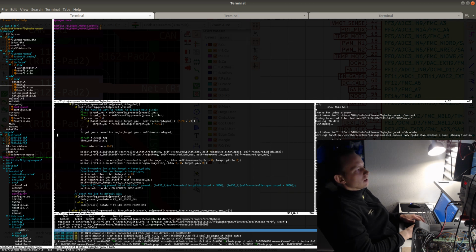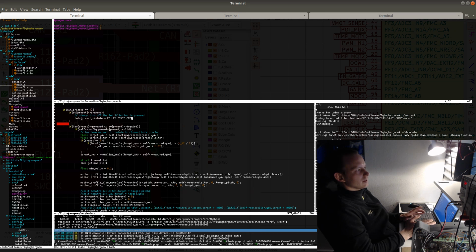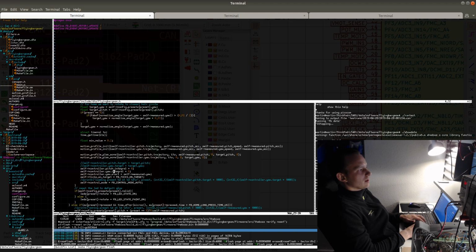It needs to be a normalized angle, which is achieved by passing it through an atan2 function, which normalizes the angle between -pi and pi. And then when I read out the trajectory, I also add the starting angle. So I saved the starting angle for yaw, and this makes it possible to use the same profile planning function for the angle, which can otherwise wrap around.